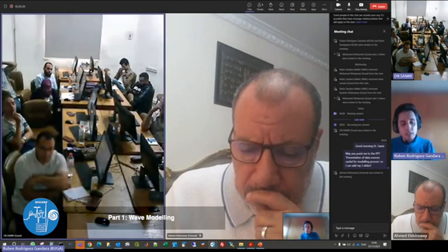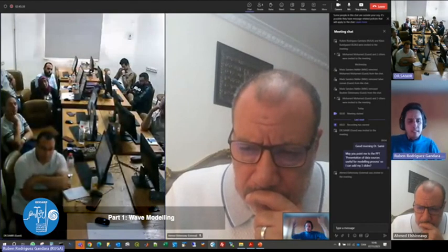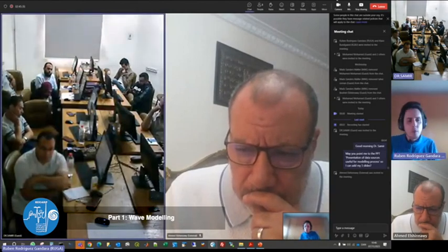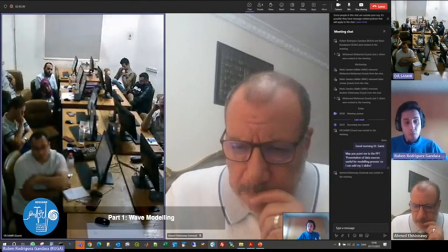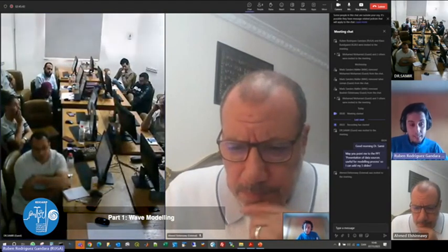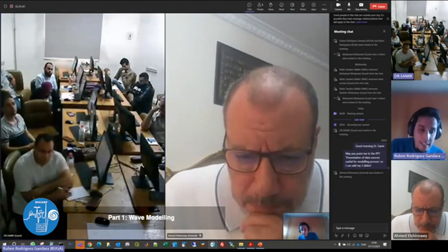Remember, operational conditions are the normal conditions, so this is just very simple statistics of grouping the data in directions or months or whatever. It gives you a bulk idea of how the waves will behave in the area throughout the year. With the extremes, what you are doing is defining the design condition.